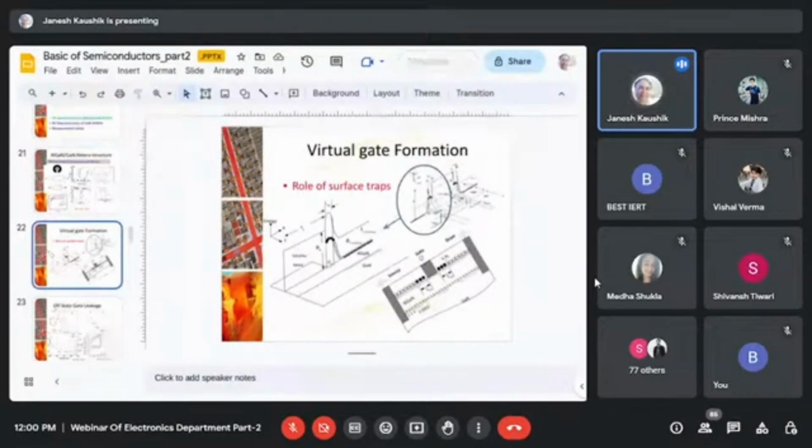Actually, at the AlGaN top surface, surface states are present. They are positively charged when there is electrical neutrality across all the surfaces, meaning there is an equilibrium condition, no voltage is applied, and this positive surface charge has compensated the negative polarization charges. But the moment we apply a voltage, for example at a Schottky metal gate, the nearby surface states capture electrons and become neutral again.